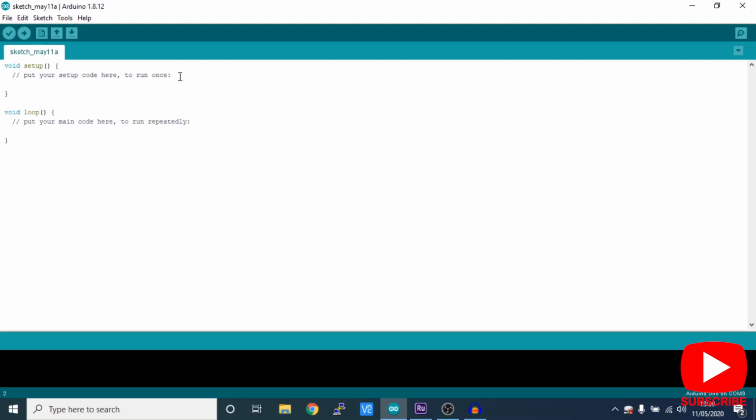So in this area here that's titled void setup, this is where we're going to put things that we need to run once, or things that we need to define for the void loop to run. So it's exactly that. We're setting up what we need the microcontroller to know. The void loop literally runs through the code, so it'll start at the top, run down to the bottom, then it'll loop back around. Hopefully this will make more sense as we go on.